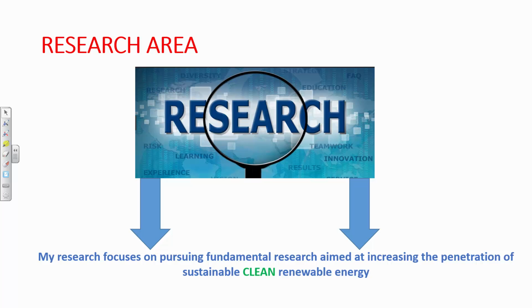Also, they have something called the demand management technique. They have smart meters, so they tell their customers, right now you are paying this amount of money. If you are using electricity from 12 noon to 2 p.m., you are paying, let's say, 10 cents per kilowatt hour. But if you use electricity during the night, you will pay less. So customers will automatically adjust their energy consumption. They try to use more energy during the night. That will reduce the peak, and if they are generating more electricity from the wind during the night, they have enough demand. So all those techniques, demand management and energy storage, we need in order to increase the penetration of renewable energy sources.